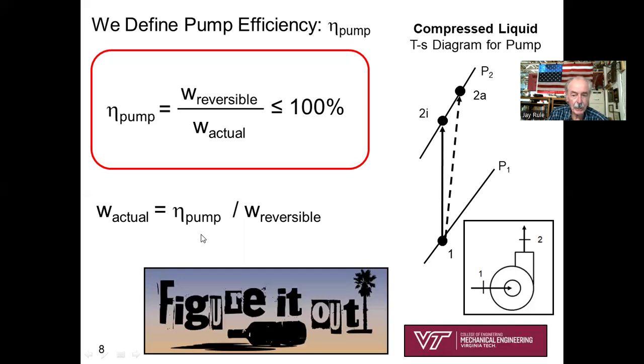I'm going to show you, I hope coming up, a slide with some real honest-to-goodness ways to visualize a given pump efficiency. Typically we're given pump efficiency, or we determine it from what's called a pump curve. As engineers, we can calculate this reversible work, this minus the integral of VDP, using that easy formula that I talked about but didn't write down.